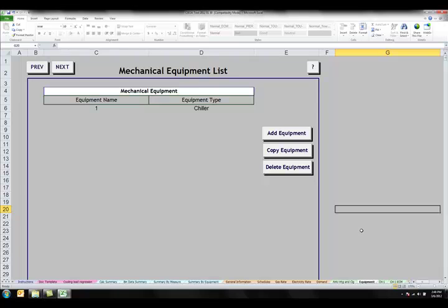The output data on the bin data summary worksheet can then be used for these multiple system scenarios. For example, if 1 chiller operates below 90 degrees outside air and 2 chillers operate above 90 degrees outside air temperature, then those 2 scenarios could be run, and the output on the bin data summary worksheet could be viewed for the savings results. The bin data summary worksheet is discussed in detail in another tutorial.